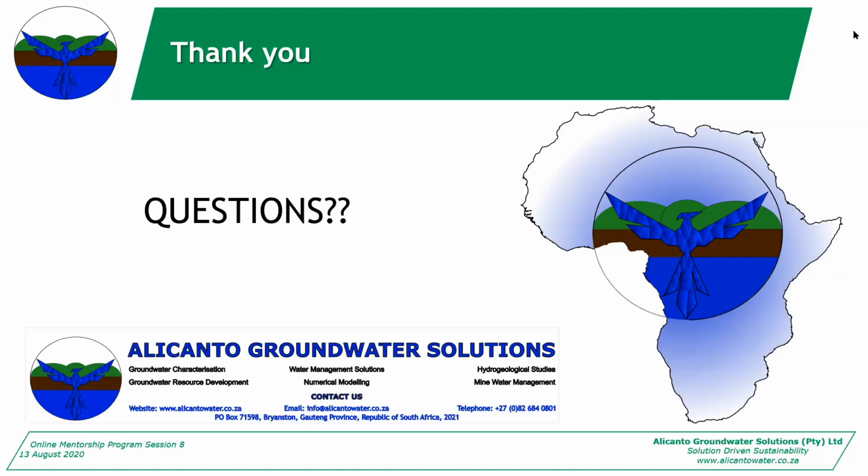Look, we covered the conceptual model in one of the previous ones, but what you do with your conceptual model, if it's a 3D system, then you represent it in 3 dimensions. Your conceptual model needs to present the core concepts of the site. Like for your case, you'd need to focus on your recharge variances, your recharge zones, and then the interaction between your upper unconfined and lower confined aquifer. So you can do that with 2D sections, or you can do a 3D conceptual model. But to put your 3D stuff into a report is quite challenging sometimes.